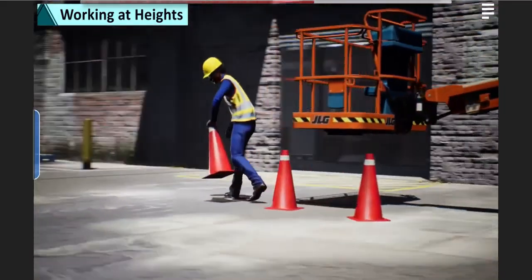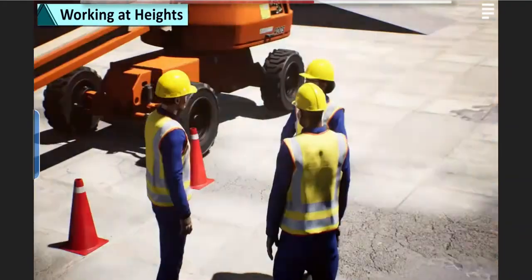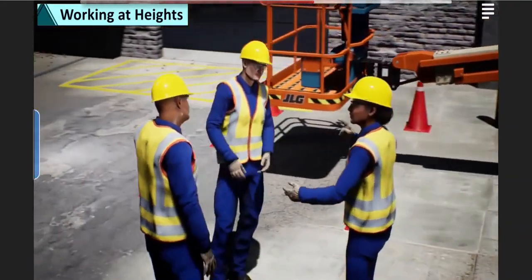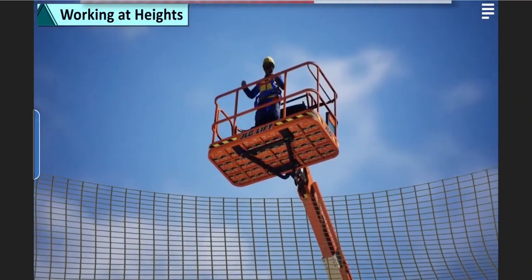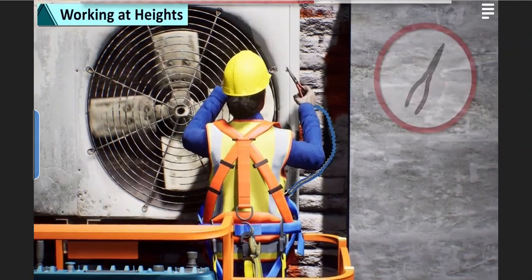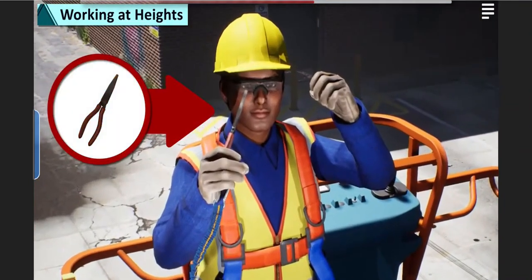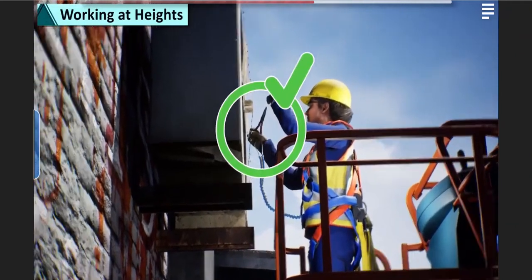Always cordon off the area below the platform and restrict access to that area when possible, and make sure personnel in the area are alerted before the MEWP moves. Use safety devices like lanyards and nets to reduce the risk of dropped object hazards. MEWP platforms should only ever be used to carry tools or materials which are needed for the operation and can be safely handled by a person working from the platform.